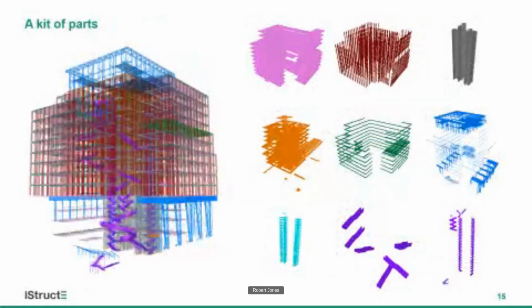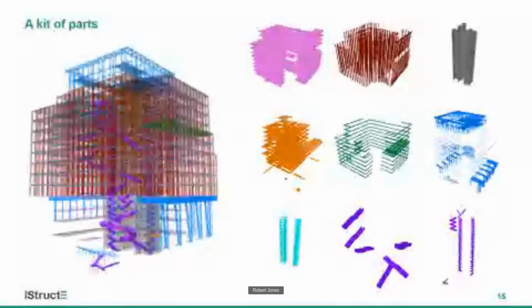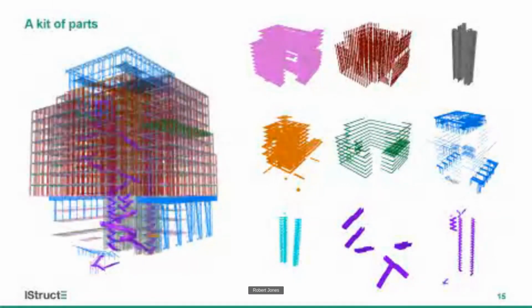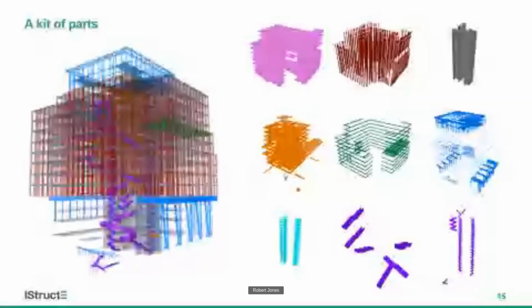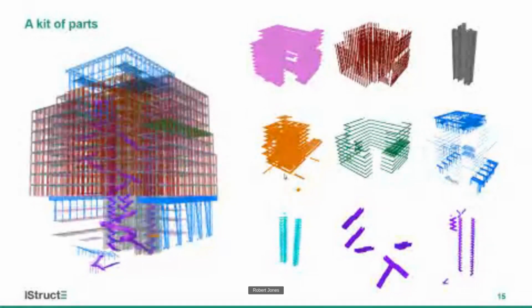What we ended up with as well when we went into stage 5, working with Keith and their team, was they brought in even more precast. So they brought in twin wall in the cores over here. They also brought in precast lattice planks for the heart slabs above level 5 and above, as a kind of permanent formwork for the flat slabs in there. And so really 2/3 of the building is prefabricated with a little bit of in situ stitching to the top surface of those slabs.